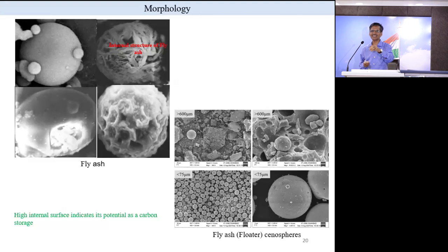So that's why fly ash is called a mineral admixture. That is why in cement and concrete everywhere they are using it because of these advantages. But for geotechnical engineering, it does not have strength. If it just becomes dry, it tries to fly. Then you put extra water, sprinkle water, all these things you have to do, that we don't do in ordinary soil. So this is one, light, spherical type, and that's why I also call it, it behaves like a dispersive soil.